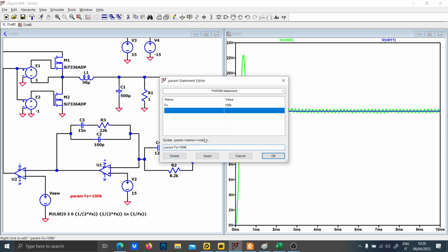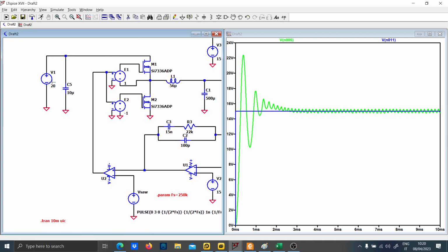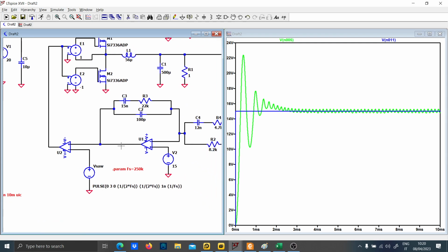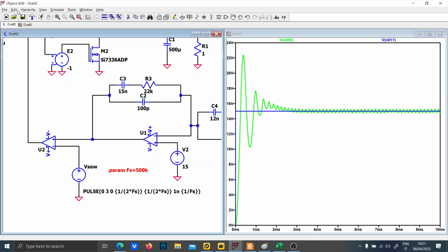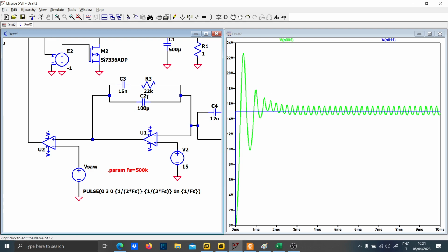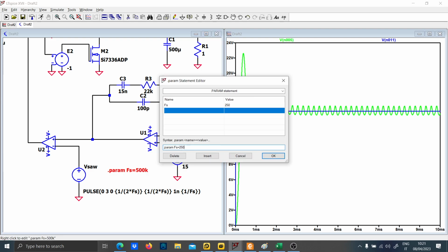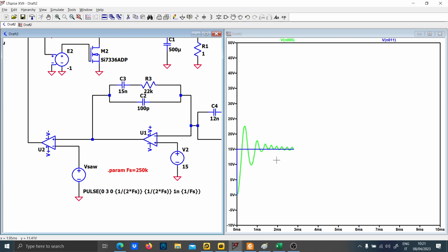We can increase the switching frequency in order to reduce the ripple, since silicon MOSFETs and low power MOSFETs can go even to higher frequencies, even like 50 kHz. It is true that you should redesign. I don't know if it is going to work, because you should redesign the compensator to make it work at this frequency.